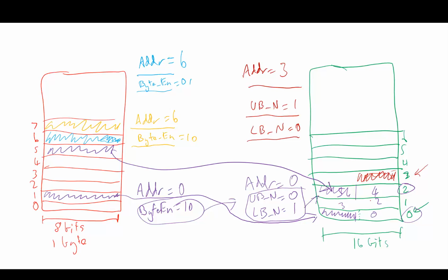So if we are converting each of these byte addresses on the left to the equivalent half word address on the right for the SRAM chip, this would be address 0, 0, then 1, 1, 2, 2, 3, 3. So you should see a pattern that's occurring there.